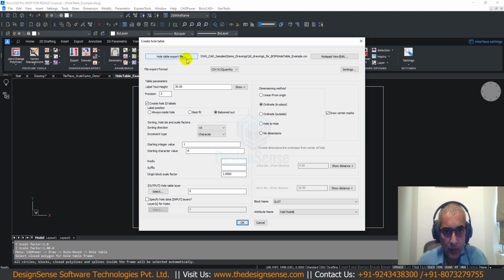One of the important outputs of the whole table command is the CSV file again, because like I said, most of your data eventually goes into Excel. The whole table format also is important and worth mentioning here. By default it is the quantity and the XY positions, but we also have two sub programs, milling XY and Siemens sub program. So we leave first the default.